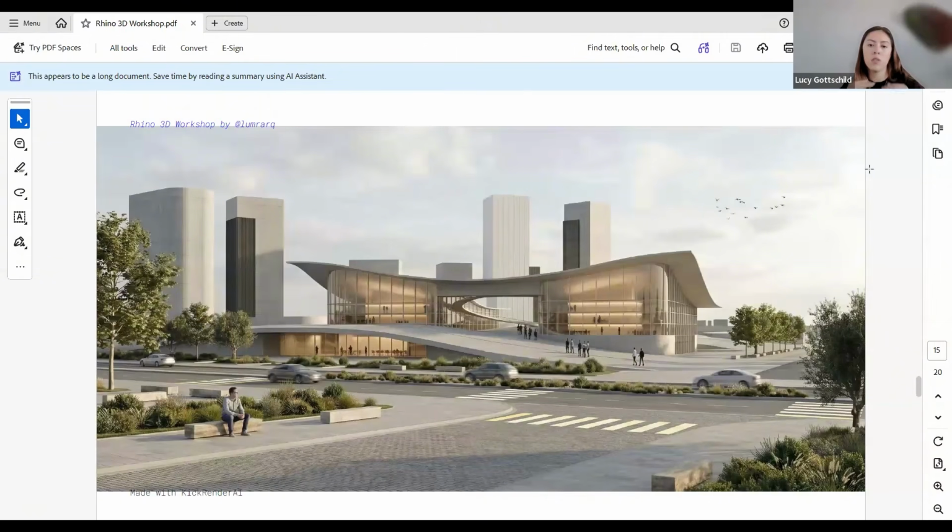For example, the floorings, that's something that you can do by using the face borders of the volumes and then doing the planar surface. Then that planar surface, you extrude it and copy it into the several levels. All these commands we already know from the little time that we were connected. So I encourage you to continue and keep following a model that can end up like this.